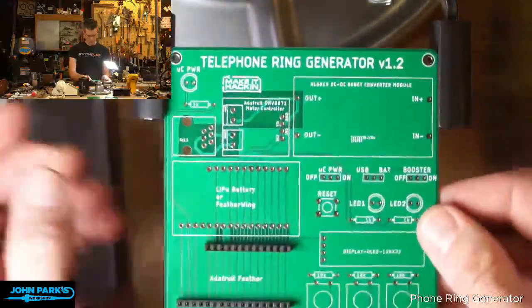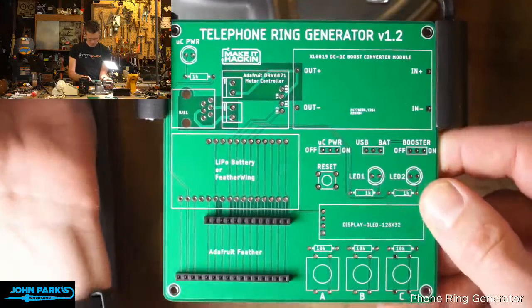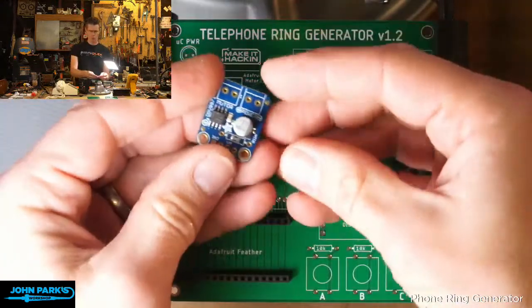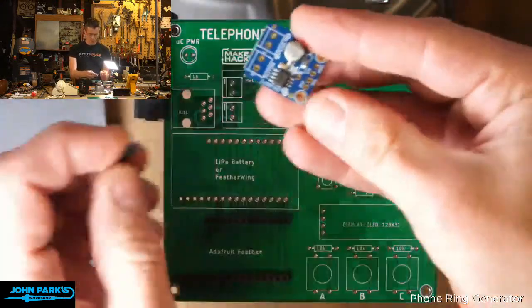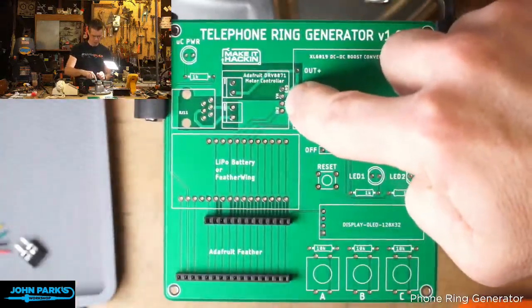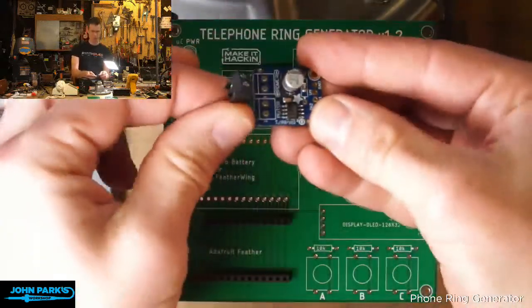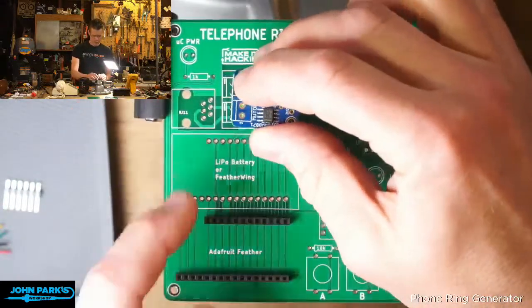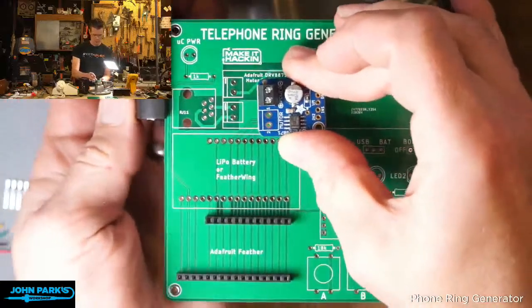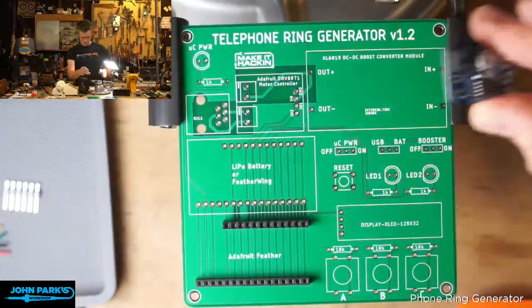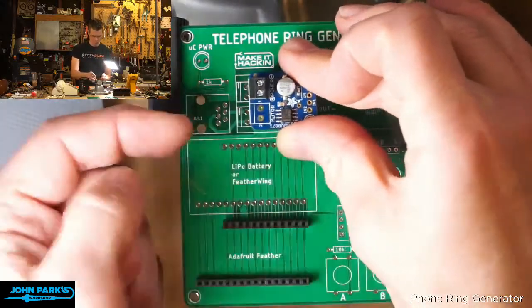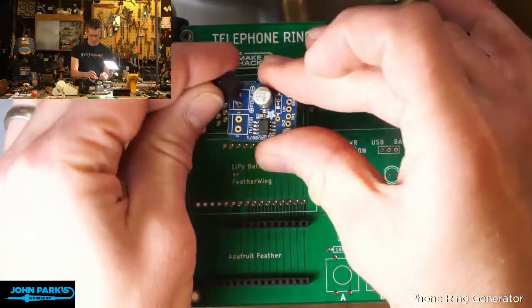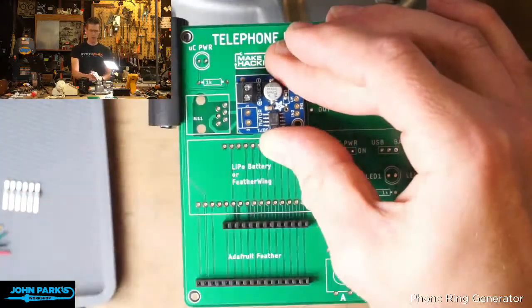And the next thing we'll do is the driver controller, the motor driver controller. So this has header pins that connect it to the board, and then it uses these little terminal blocks, usually to connect things to them. It's not really necessary in this case, but it is the design. I think what Andrew has this set up as, looking at the pictures, is some small jumper wires running from the board up into those terminal blocks. I think you could also do it just with a straight wire shot down through there, but I'll do it this way because that does give us the opportunity to plug other stuff into that, at least for testing.